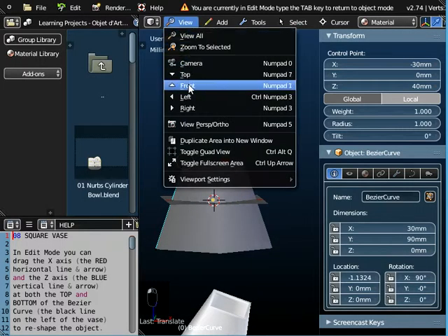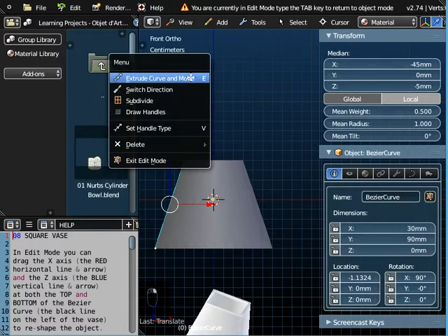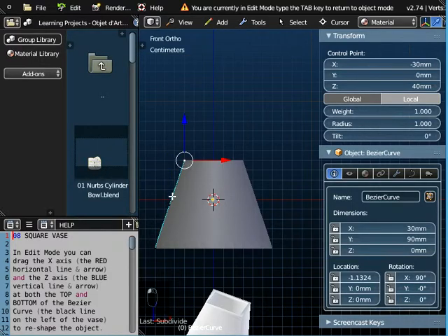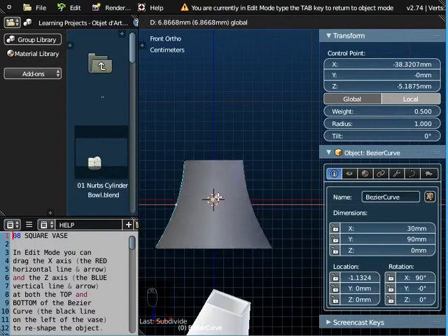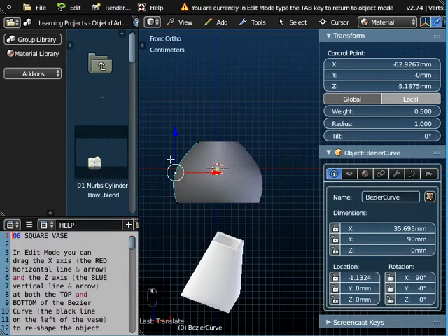Now if you wanted to modify this by changing the shape at some midpoint of this object, what you could do is, if we highlight the two control points, and I'm holding down the shift key on my keyboard to select the two control points, if I right click and click subdivide, I'll get an extra new control point in the middle there, and I can now manipulate this object and change it from a straight line on this end to a curve.